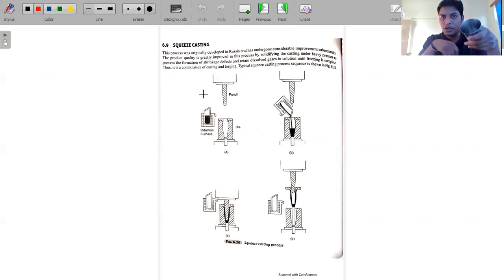Another thing is that it should be hollow. It's not like a die where I fill the material inside and it becomes solid. Here it's hollow. Whatever the thickness is has been reduced, and the hollow section is initially large in cross-sectional area, then decreases with respect to the length up to here, and then it is constant. Accordingly, I am creating this type of plunger.